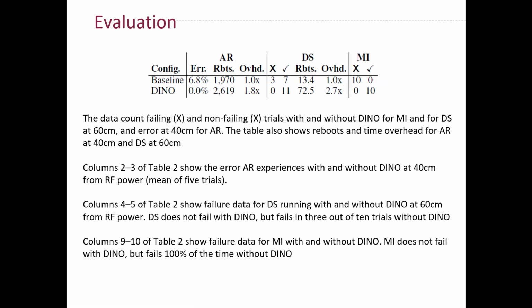MIDI fails 100% of the time without DINO, and it processes just 975 messages on average before failing. So MIDI reveals an important feature of DINO, which is that naively porting code to an intermittent context threatens functionality. But with DINO, failure-free porting requires placing just a few task boundaries.